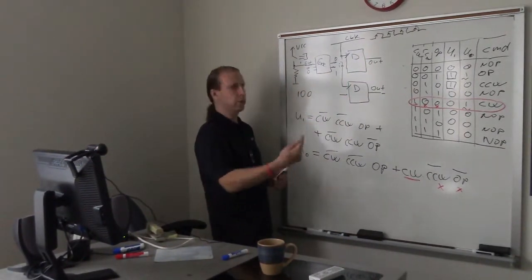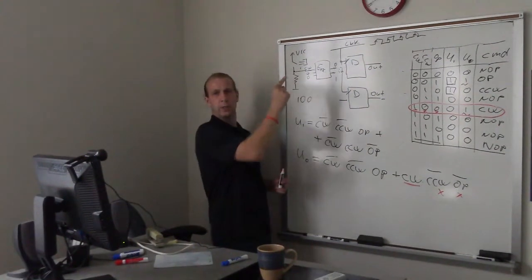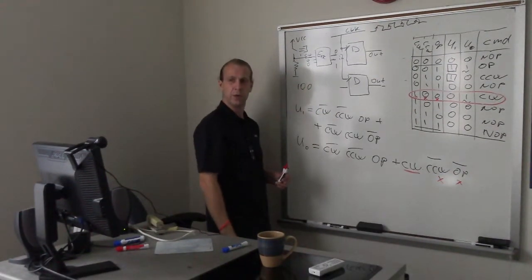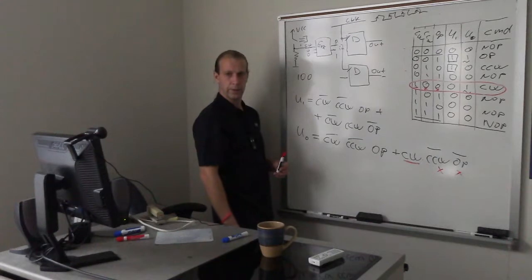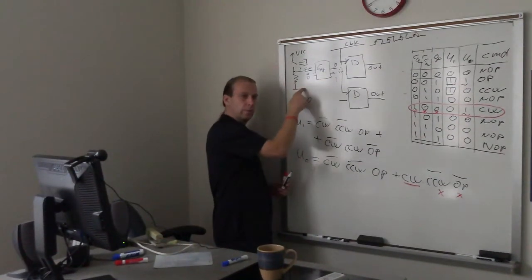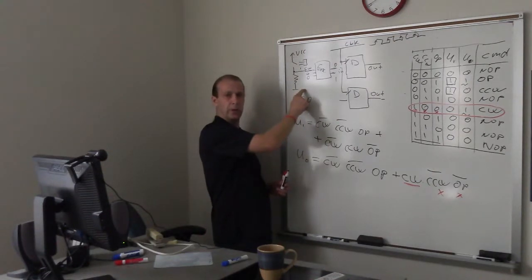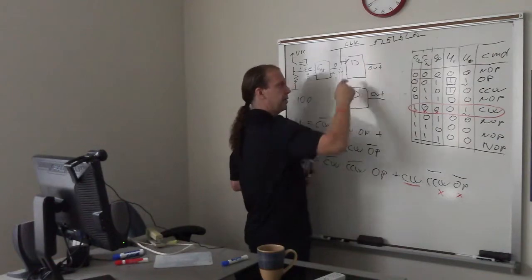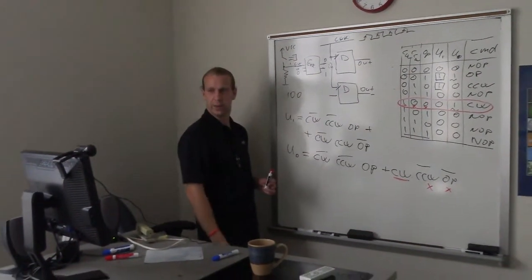Our intent is to press the push button, release it, and make the state of the finite state machine change only from A to B. In fact, while we press and hold for just a very short amount of time and then release it, there will be many clock cycles and many transitions of the state of the finite state machine.